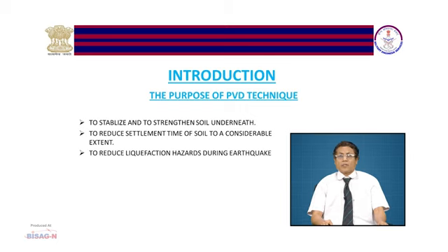During earthquake, there may be possibility of increasing the pore water pressure. So, through PVD we can reduce the pore water pressure by releasing the underground water, through it give the safety factor towards the soil.